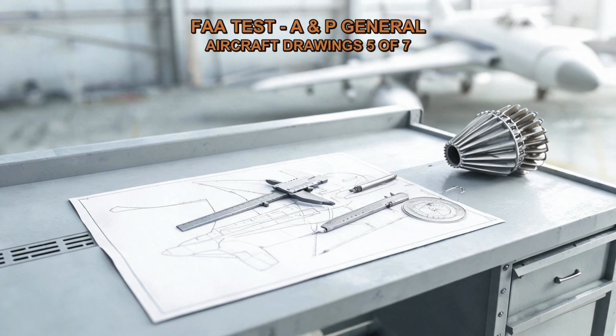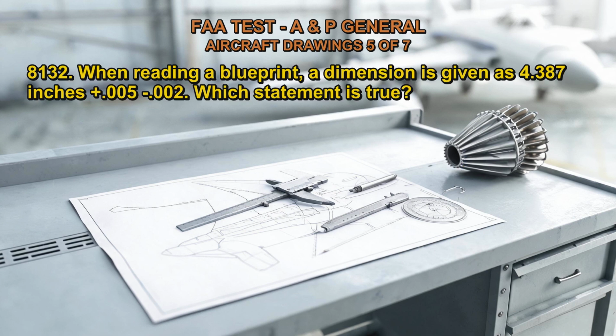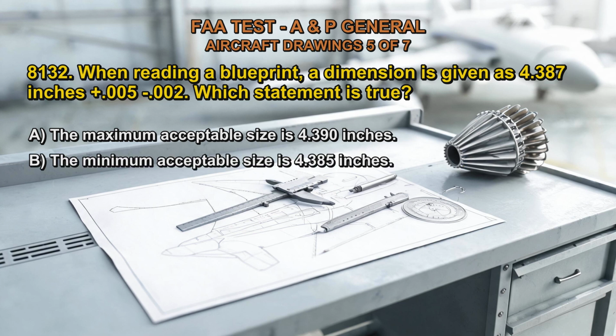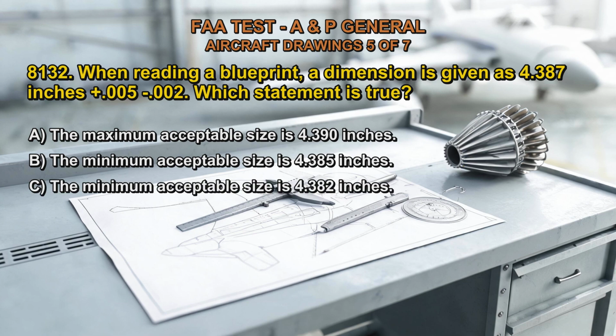8132. When reading a blueprint, a dimension is given as 4.387 inches plus 0.005 minus 0.002. Which statement is true? A. The maximum acceptable size is 4.390 inches. B. The minimum acceptable size is 4.385 inches. C. The minimum acceptable size is 4.382 inches.